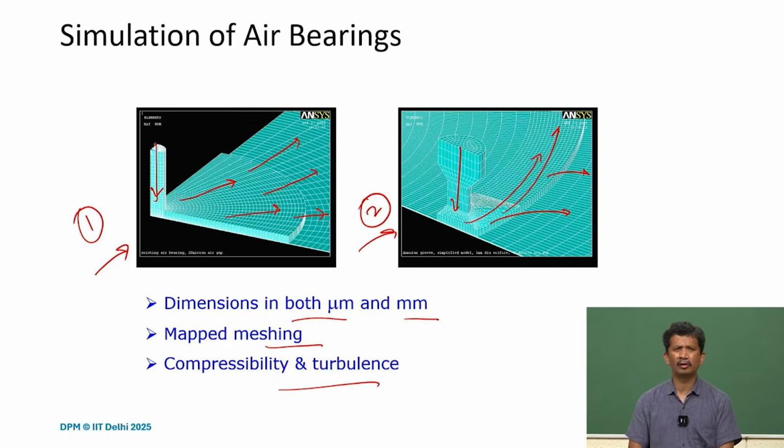So here we have more flexibility. In analytical models, we always try to be conservative. We assume laminar flows and then try to find closed solutions. But when we are working with the CFD packages, we have more freedom, and with time we can define what kind of turbulence, what kind of other flows can happen. We can always define our models in that way, get the results and compare how it is deviating.